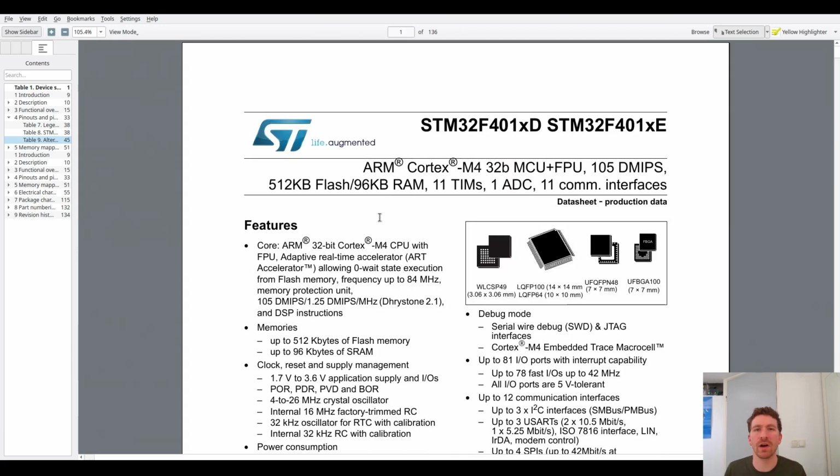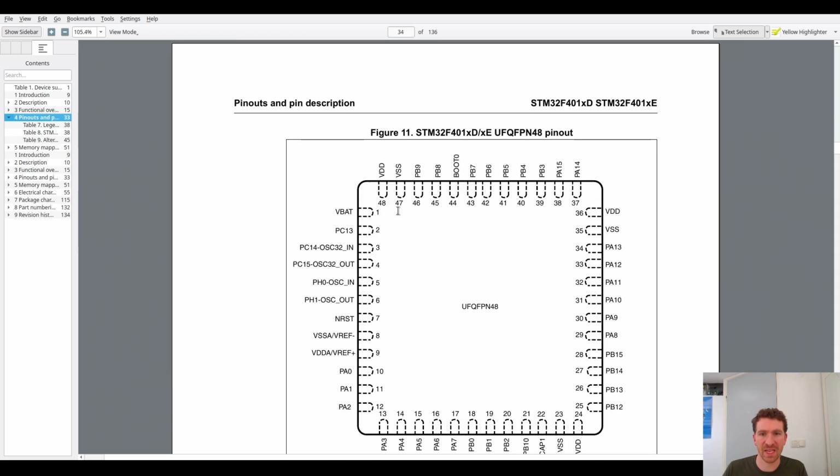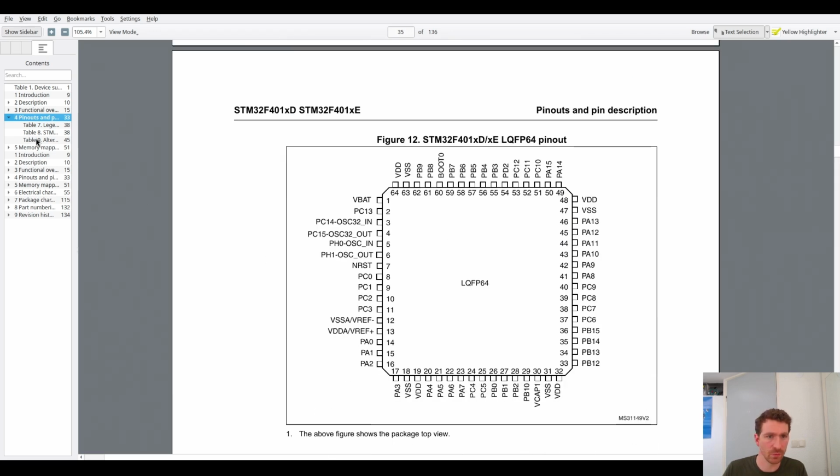You can see the datasheet contains all of the high level information about this chip, all of the measurements and the exact pin layouts, and all the stuff you need mechanically and electrically, and all of the big understandings that you would need if you're going to throw this chip into something and use it in a product. All the various disciplines would need to read the same document and figure out, is it going to work for our purpose? The main thing that it has for us is the pinouts, and of course this shows you mechanically and electrically the pinouts and all of that kind of stuff.